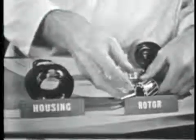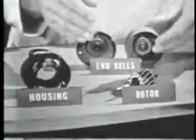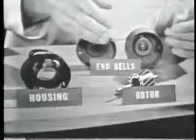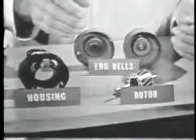Simplicity of construction, which of course leads to lower cost of manufacture, and a very rugged design, makes the induction motor a very popular one. There are no wires on the rotor to burn out, no brushes to wear, no commutator to get scratched or pitted. All in all, a pretty good motor. Of course, it's not perfect for every application. It does have certain limitations, but even so, it's used quite extensively.